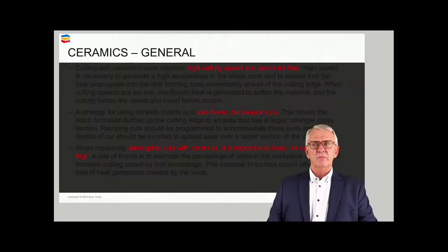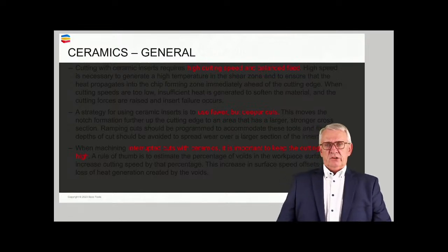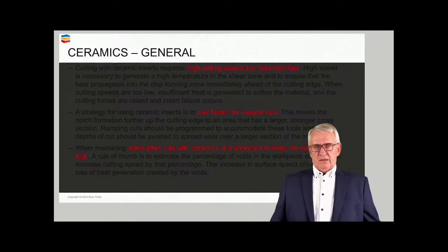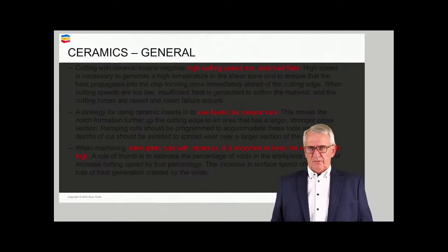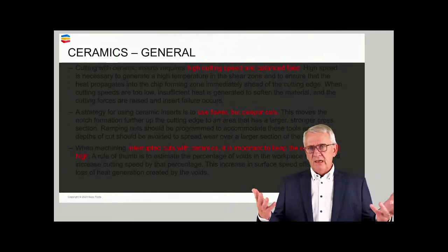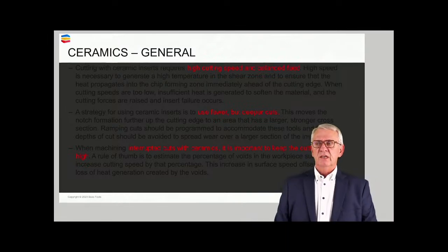How do we use ceramics? High cutting speeds with balanced feeds is the thing to worry about. In general, think in terms of bigger depths of cut, which some of the older people here in the audience will perhaps say, bigger depth of cut. We talk about ceramics, aren't we? Yeah, we talk about ceramics, but still think in terms of bigger depths of cut.